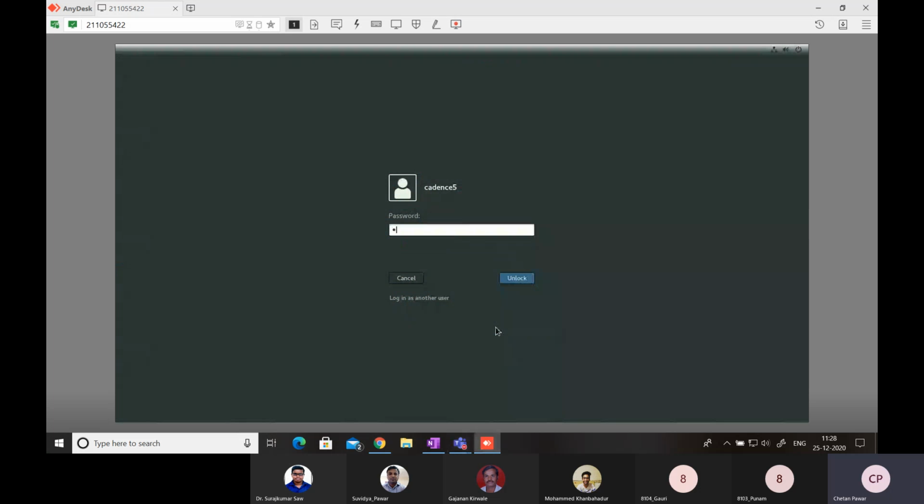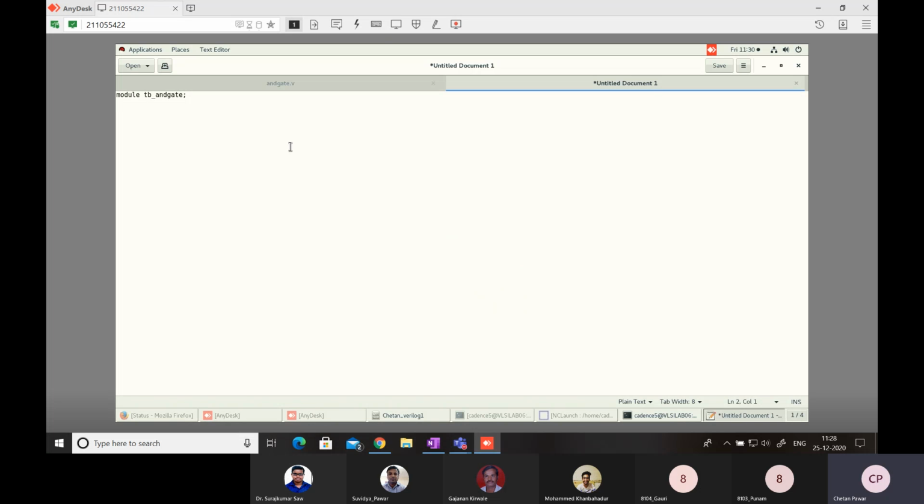So in our test bench, so this A and B, I will assign value to this A and B. So I'm using reg data type for A and B. Okay. And I'm using wire data type for C because I'm driving that wire by applying those inputs. So for C, I'm using a wire as a data type. Okay.